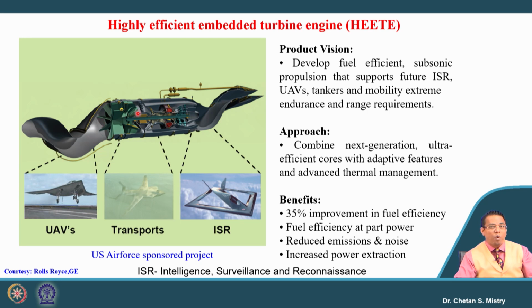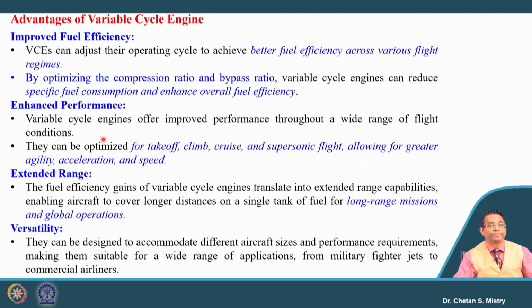So here we have the engine, and this is representing the intake. Basically, IR signatures are captured mainly at the entry or inlet, secondly at the exit from the nozzle, and third from the turbine section. So a lot of research is going on of a proprietary nature, exploring the possibility of such engines being applied for UAVs, transport and ISR.